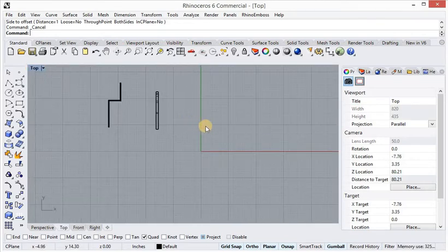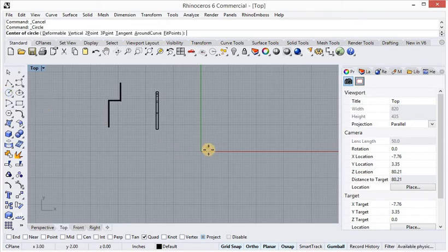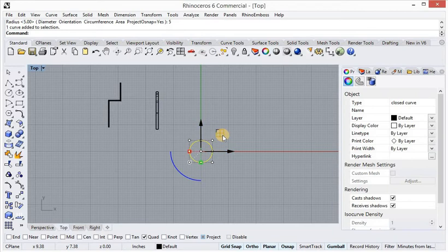Now I am going to take the Circle tool. Click the Circle tool, click here in the middle of the viewport. You can click anywhere, it is just for practice. And give the radius 5 inch for a 10 inch diameter in the command bar, because radius is half of the diameter. The line should be selected before applying any command.